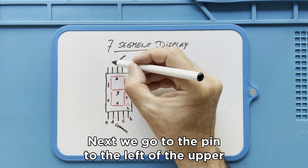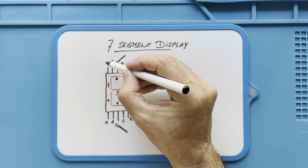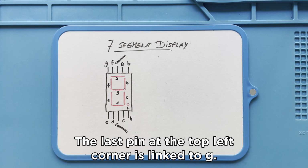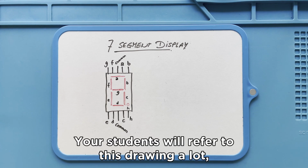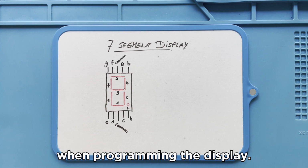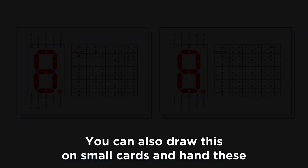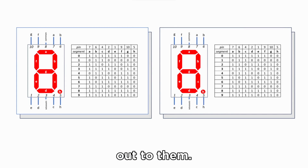Now we go to the pin to the left of the upper common cathode pin, and this is linked to the segment F. The last pin, at the top left corner, is linked to G. Your students will refer to this drawing a lot when programming the display, so best to keep this close at hand. You can also draw this on small cards and hand these out to them.